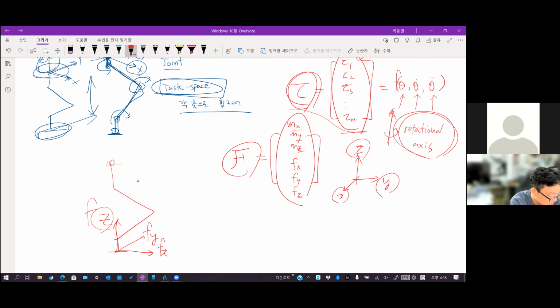So in the case of you moving this leg in this or this direction, in the humanoid it should have very precise position control in the xy direction. But in the case of the z direction, it is better to control it very softly or compliantly, because of the damping effect.